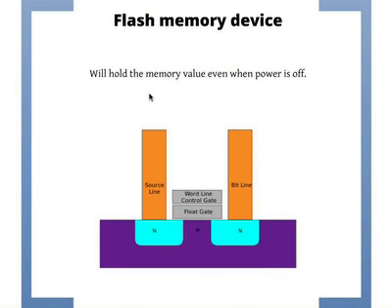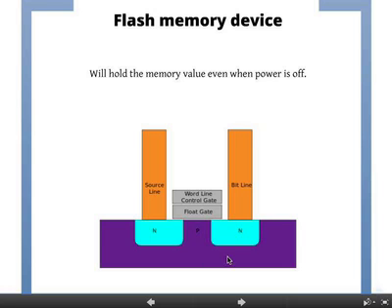Okay. The flash memory. This is what IM Flash makes here. So you guys should know what it is at least. Okay. It's actually very simple. It's essentially the MOSFET structure. So you have an N source, N drain, and you have some P-type substrate. Okay. And you have 2 gates. That's what's special here. You have what's called a floating gate. So it's an electrode, a conducting thing, that's separated from the channel by a very thin oxide shown here. But you also have a control gate on top. So you have 2 gates sitting next to each other, and they're separated by an insulator.